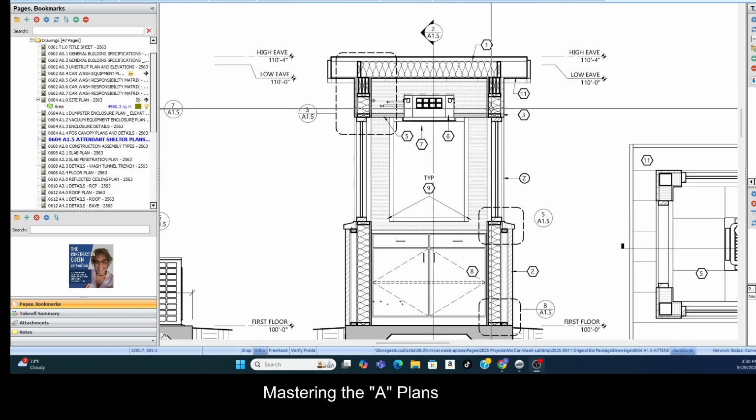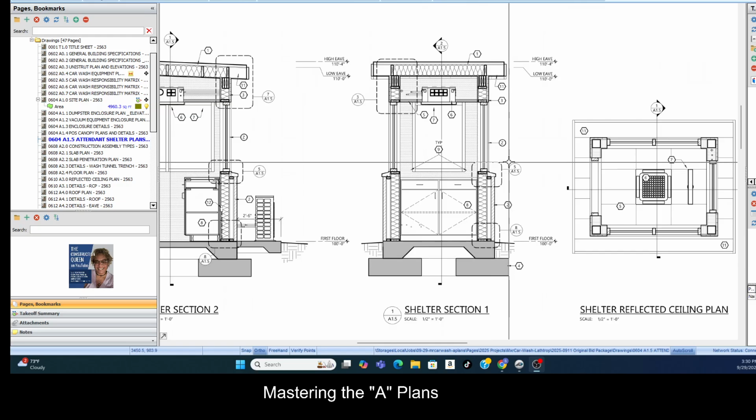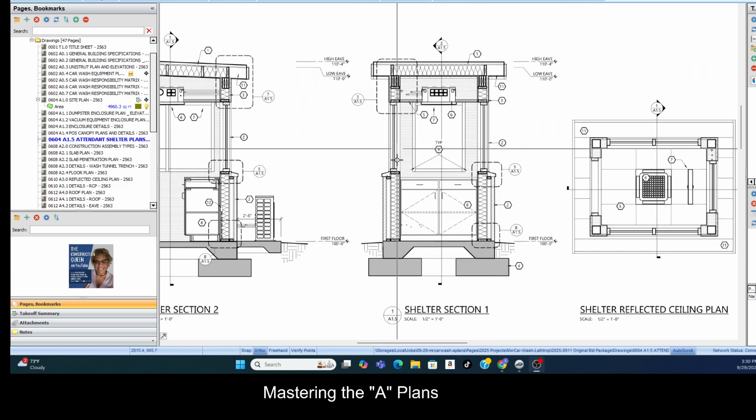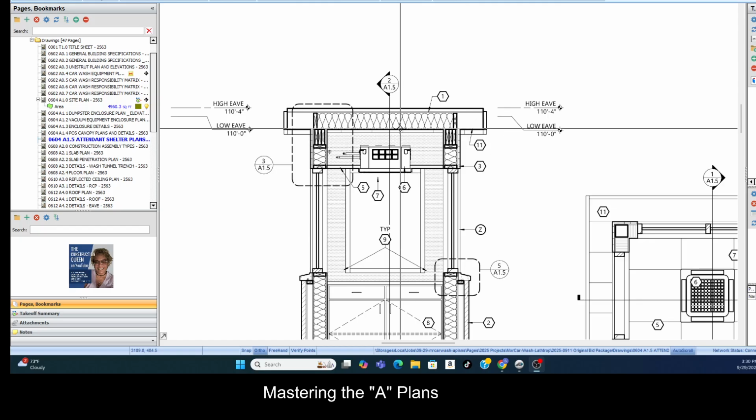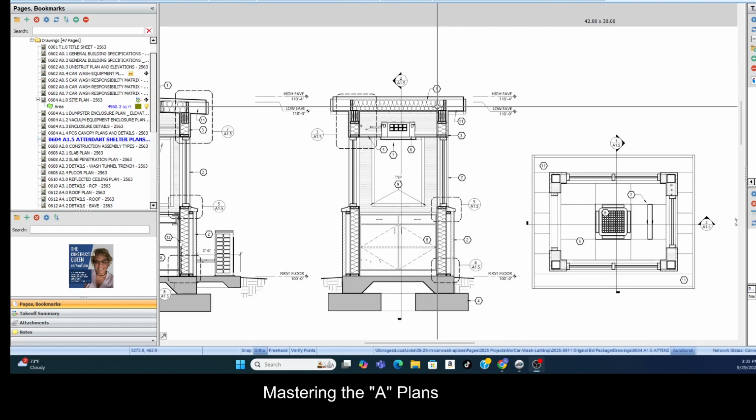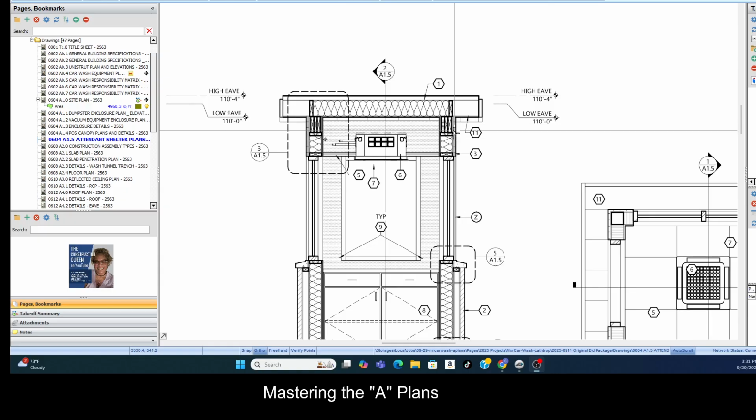And we see everything. We see maybe that's a window, maybe I don't know what all of this is, but we see the interior construction of that. All of the walls below the window. Now, if we're the framer, which is why we have this, because I need to frame these walls and figure out what's going on here. Okay, so if I'm the framer, I can use this view to determine how many linear feet of wall below the window, how many above the window, above the, oh my goodness, I'm losing it, the header. Okay, how much above the header?